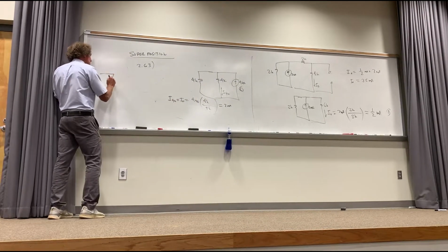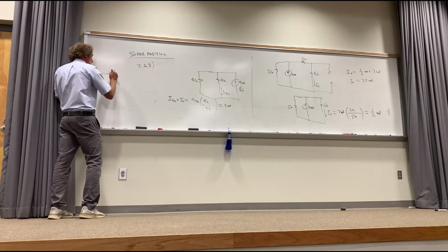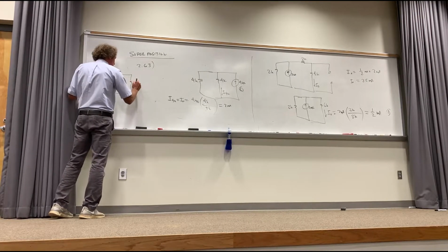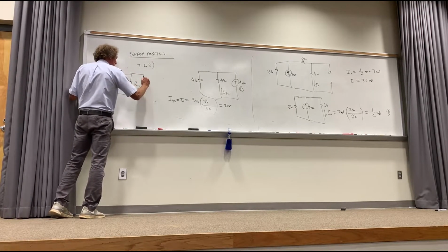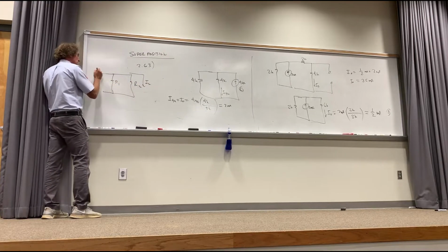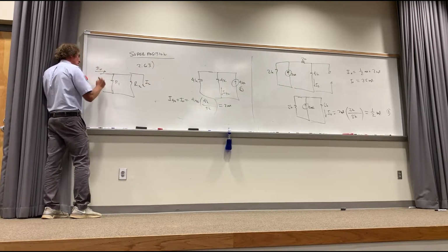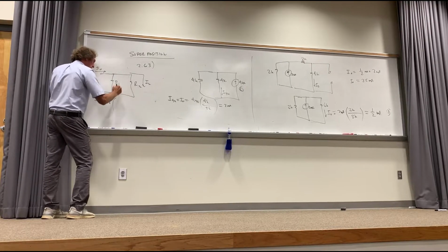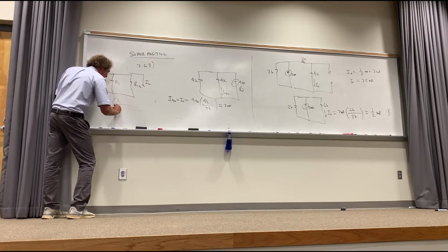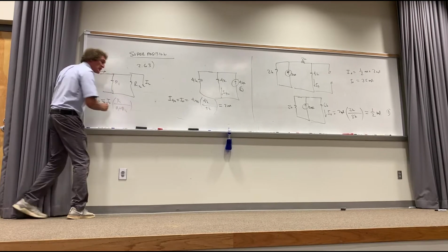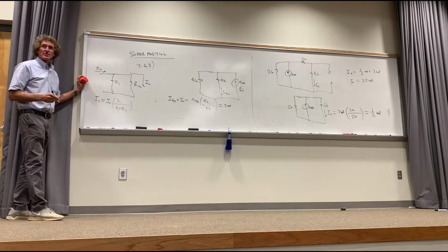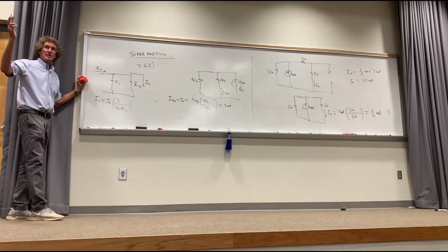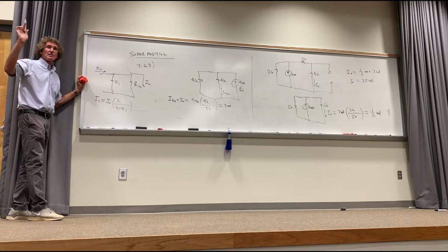If you have two resistors, R1 and R2, and you wanted the current through this, I2, if there's a net current flowing into it of I0, the current through I2 would be equal to that value I0 times the opposite resistor over the sum of the two. That's current division. We covered that a couple lectures ago. Y'all remember this? Can you see what I wrote?